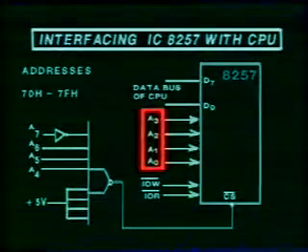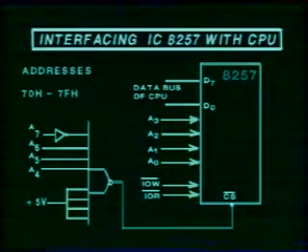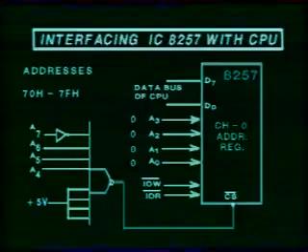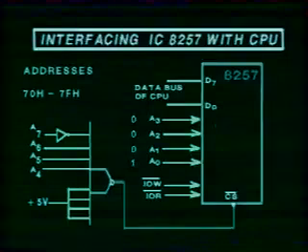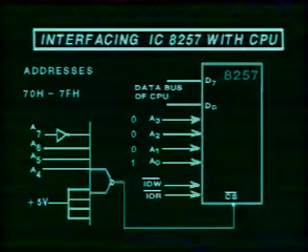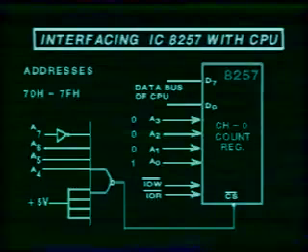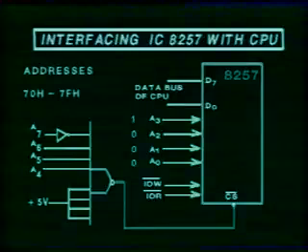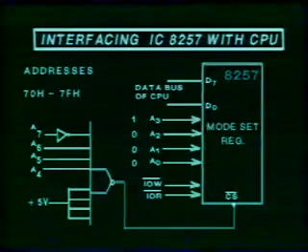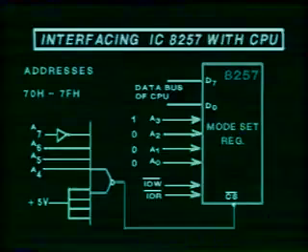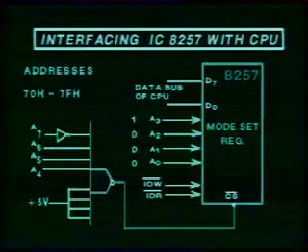The lower 4-bit combination for A3, A2, A1, A0 where all 4 are going to be zeros indicates the address register of channel 0. A 0001 on the lower 4 bits indicates the count register of channel 0. A combination 1000 for A3 to A0 is going to indicate the mode register when we are going to output operation into the DMA controller from the CPU.